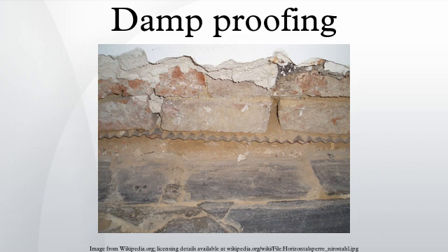Overview. Damp proofing is defined by the American Society for Testing and Materials as a material that resists the passage of water with no hydrostatic pressure, and waterproof as a treatment that resists the passage of water under pressure. Generally, damp proofing keeps moisture out of a building, whereas vapor barriers keep interior moisture from getting into walls. Moisture resistance is not necessarily absolute; it is usually defined by a specific test method, limits, and engineering tolerances.